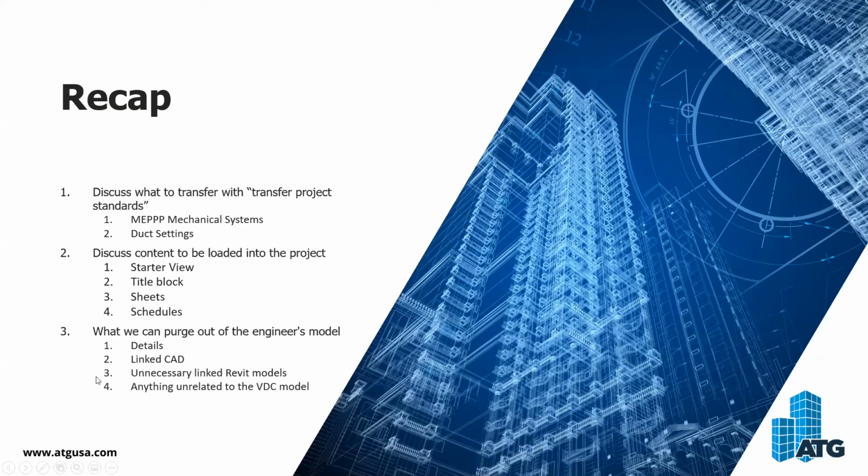Now, what you can purge out of a model, and my biggest suggestion when purging a model is to not click that Purge All tab in the Manage tab on the toolbar. That's just because you may end up utilizing some of that information or whatever may be floating around in there, and anything you added will go with it. So purge unused is something I save for the absolute last possible moment.